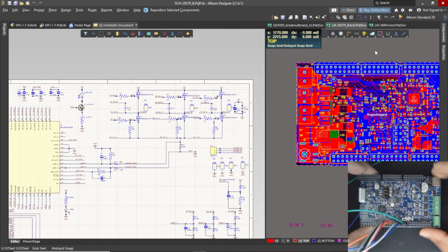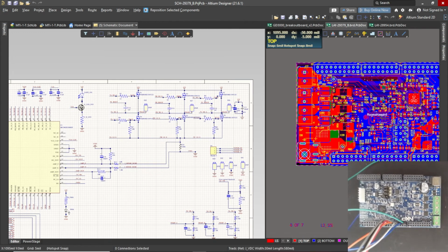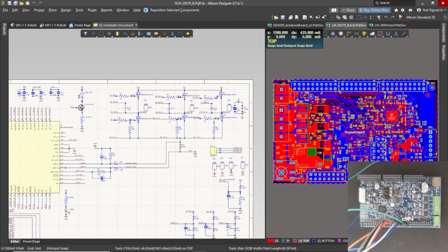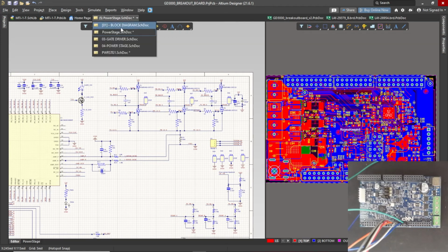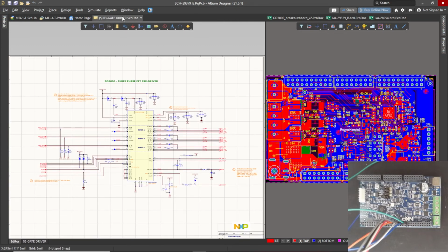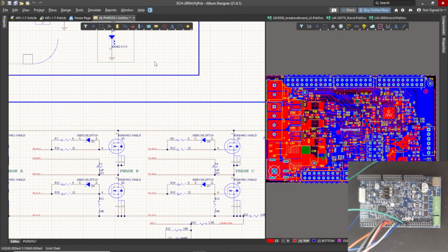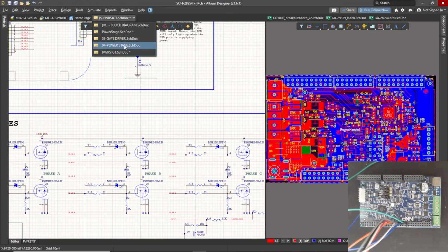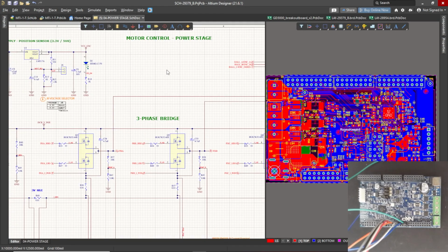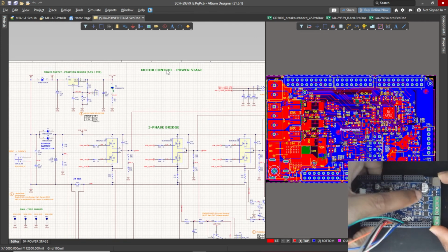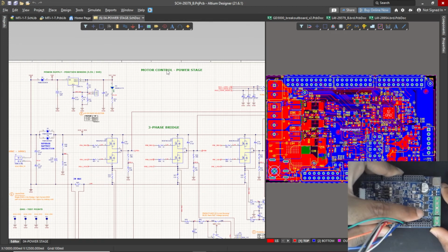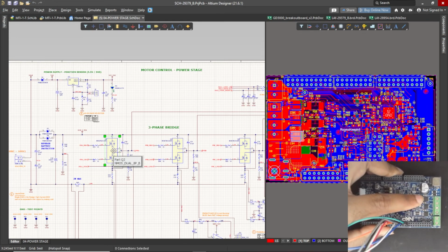So this board, NXP generally gives you the full working diagram of the schematic as well, so that you can understand it. And what they have done over here, this is one of the circuits, the gate driver. Not this one. I think it's the power stage. No, not this one. Power stage. Yeah. What they have over here is a little different. They have one MOSFET. So these are bidirectional dual MOSFETs, in the sense they have this complementary effect in here. So if you look at this diagram over here, this is one MOSFET that acts as a high side and a low side.